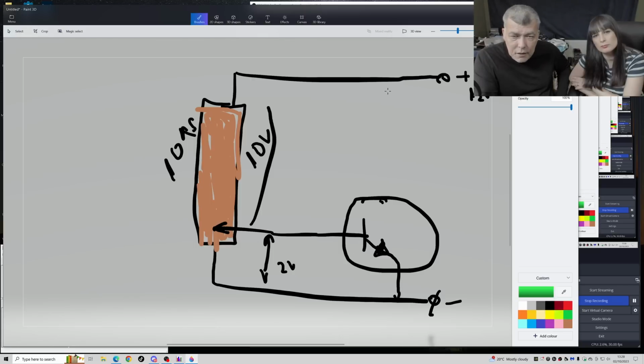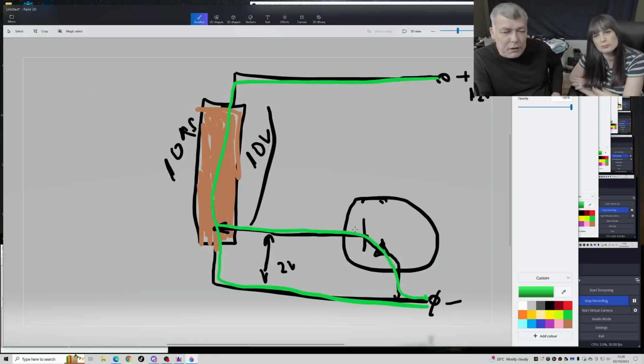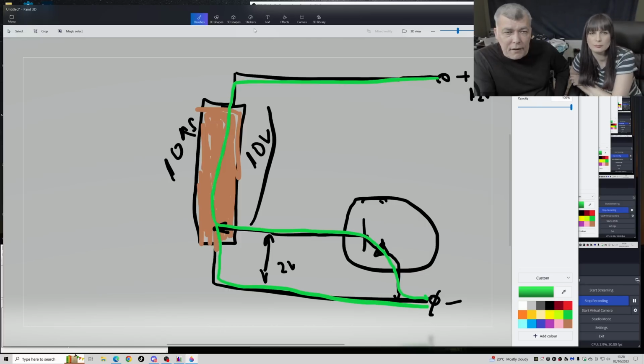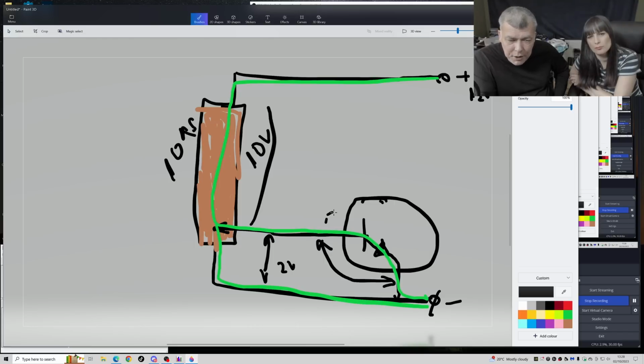And you will have this current flow. Check here, this, and this. Now, as soon as you connect the transistor, like I told you in the beginning, everything is a resistance. From here to here, you will have a resistance, because without a resistance, your current will not flow from the base to the emitter. Then you will start having a divider, a resistance in parallel mode with this resistance. From here to here, we said we have 1 kilo ohm, and you have another resistance here, which I don't know. So the voltage will be even lower here as soon as I connect the transistor.